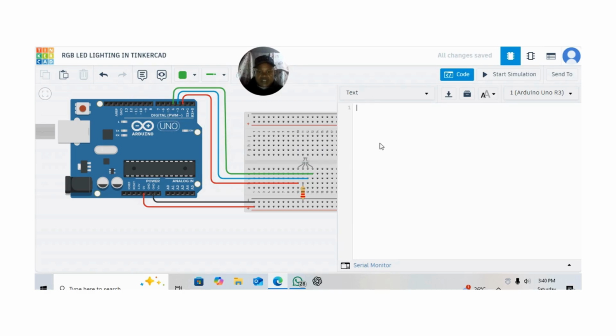Arduino. And since these pins will remain unchanged throughout execution of the program, we are going to start by specifying that it is going to be a constant. So we have that constant. Then the names of those pins, they are integers, all numerals. So we are also going to specify that.